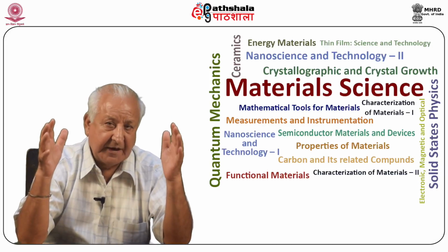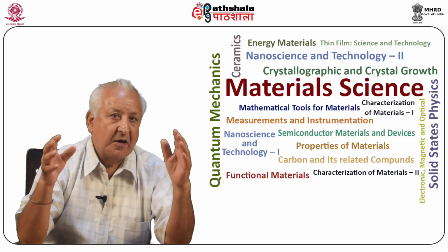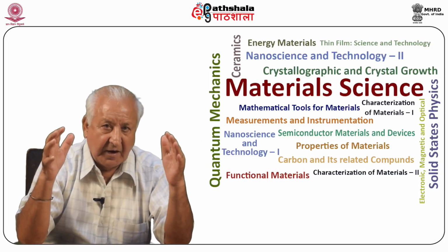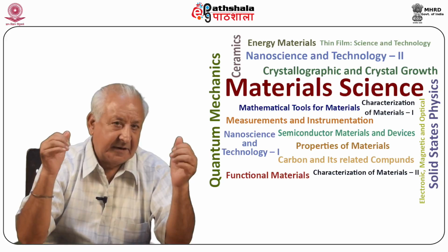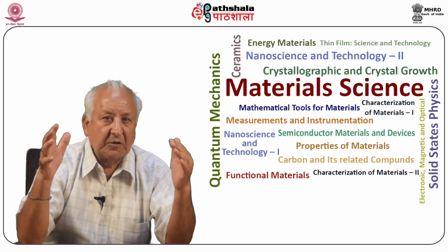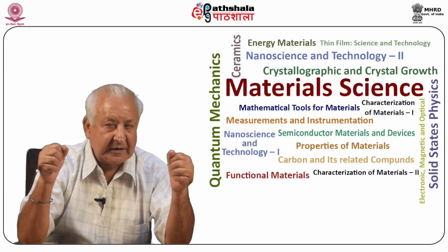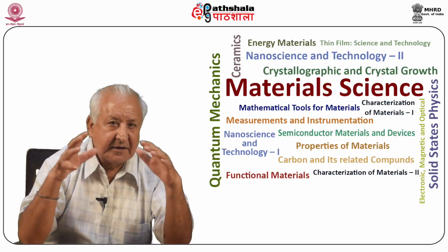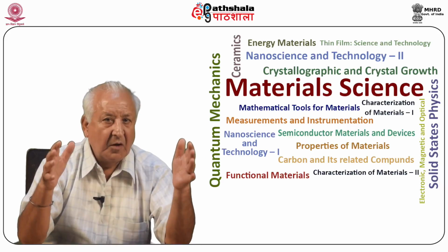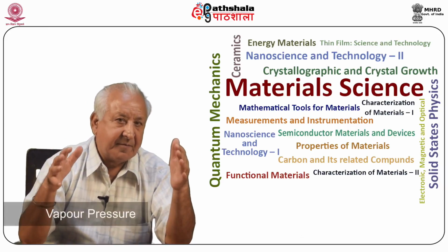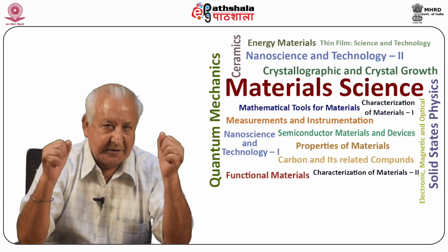Growth from molten phase is the best method for growing large crystals of high perfection faster than any other method. Melt growth normally requires that the material melts congruently, in the sense that it does not decompose below or near the melting point, and has a manageable vapor pressure at its melting point.